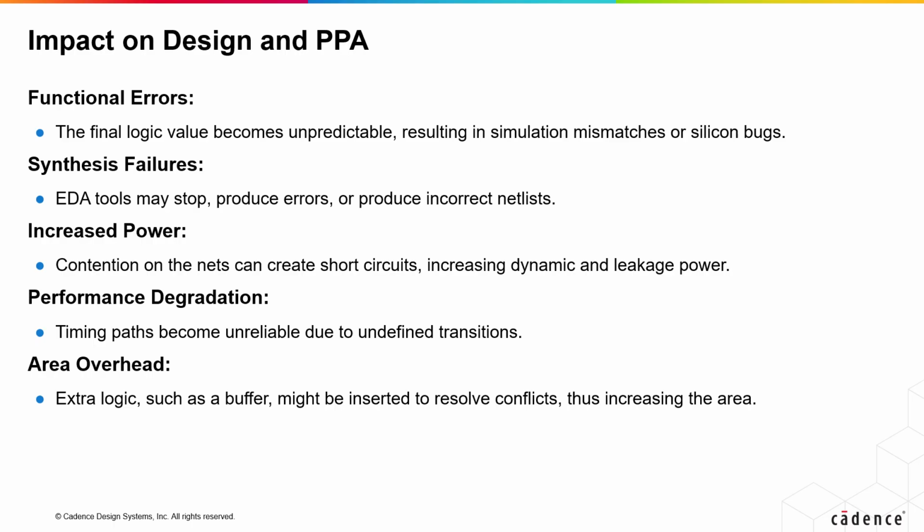These nets can create short circuits, increasing power consumption and leakage. They also affect the timing due to undefined transitions. To fix multi-driven nets, additional logic like buffers must be added, which increases the design's area.